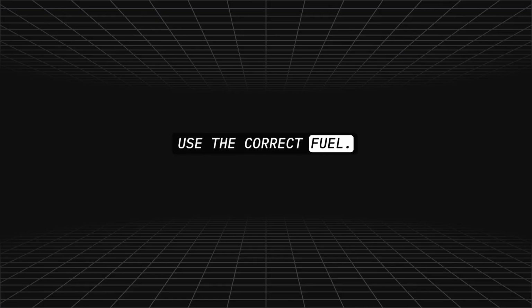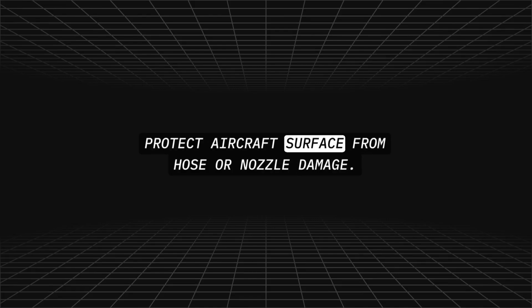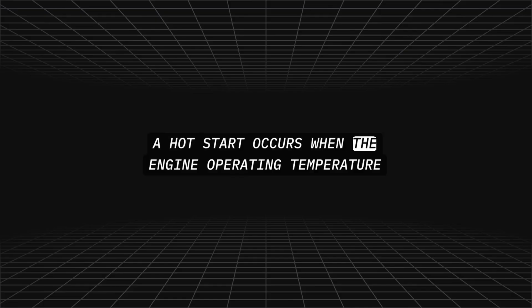Use the correct fuel. Properly ground the aircraft and refueling unit. Protect aircraft surface from hose or nozzle damage. What is meant by the term hot start when starting an aircraft turbine engine? A hot start occurs when the engine operating temperature exceeds specified limits during start.